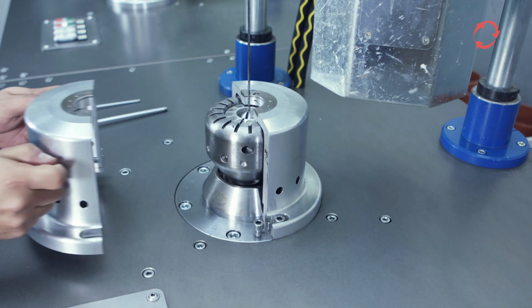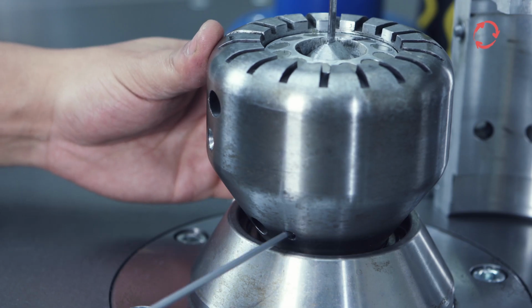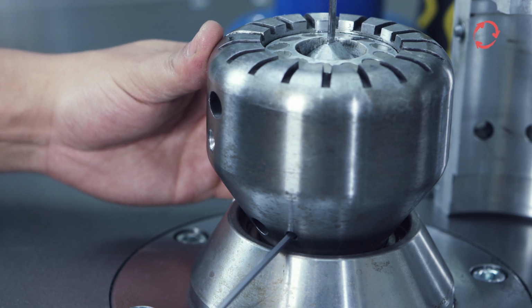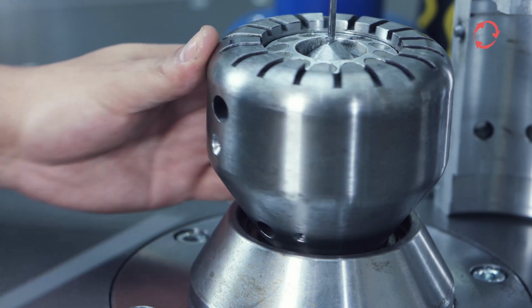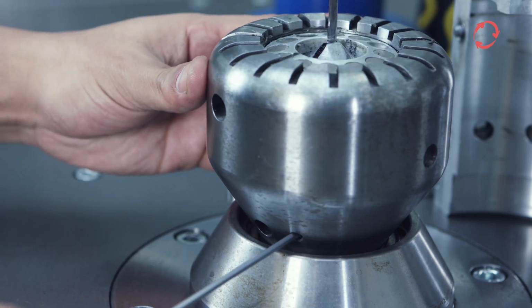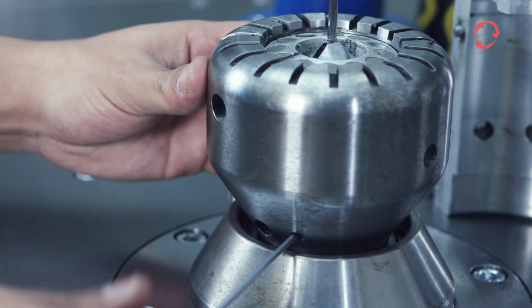The mandrel is then rotated such that two magnets are visible on the right side between the narrow side of the mandrel and the housing. The angle should be around 45 degrees. Now it's time to make a color marking. The color marking ensures the correct positioning of the mandrel and helps to avoid problems during the working process. Now remove the two clamping screws located on the hub of the winding head opposite one another for the mandrel intake with a 3mm Allen key.